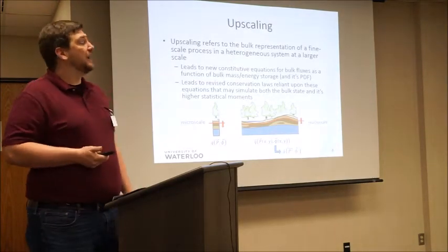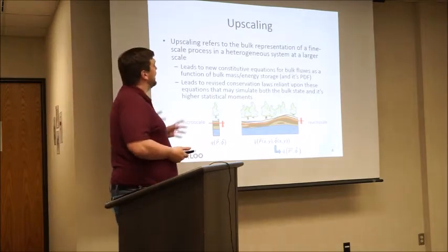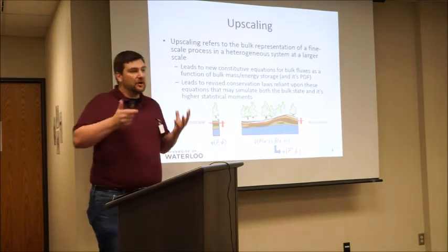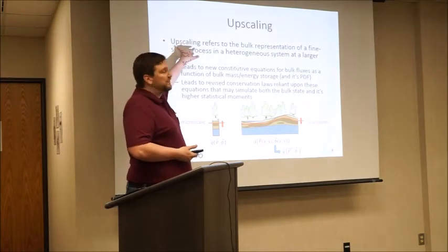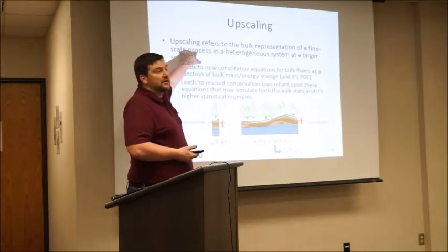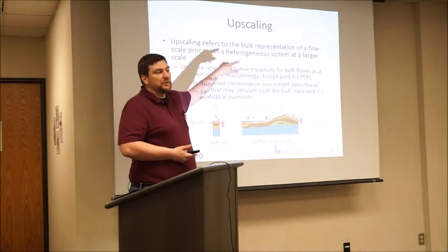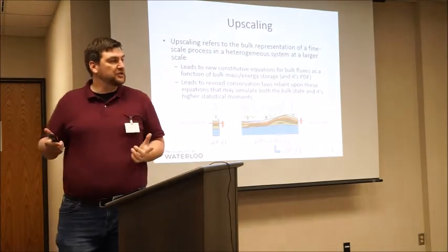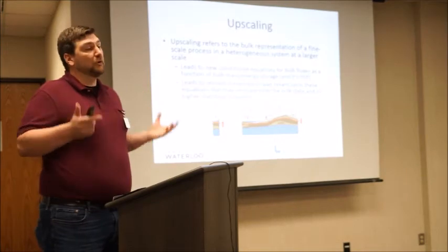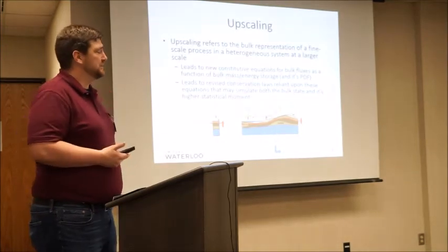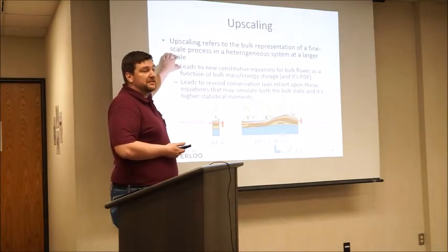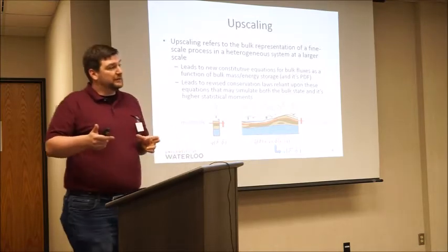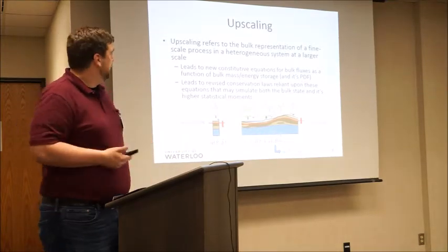So upscaling. Upscaling refers to this process of trying to take information, that understanding of what happens in detail at the fine scale, which we know reasonably well, and figure out how we determine what the rules are at the bulk scale. So we want relationships between things like bulk soil moisture and bulk fluxes in our system. We might have to bring over some information about the distribution of those properties on the landscape, but we still want to be able to characterize them in bulk at large scale.